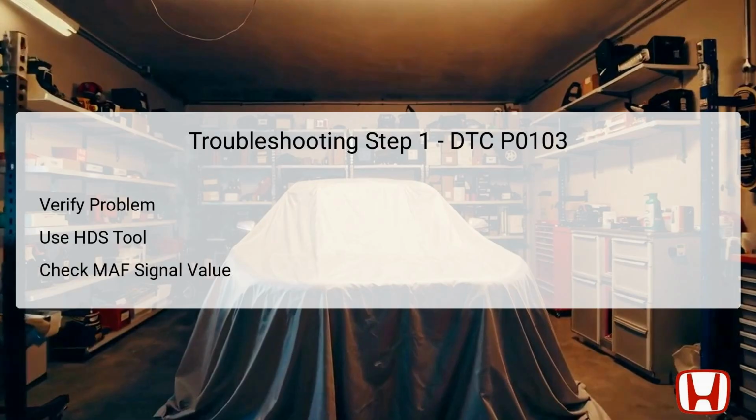The first step in troubleshooting DTC P0103 involves verifying the existence of the problem through a systematic approach using the Honda Diagnostic System, HDS. Begin by turning the vehicle's ignition to the on position and allowing the system to stabilize for at least 2 seconds. This action prepares the vehicle's onboard diagnostics, enabling accurate readings.